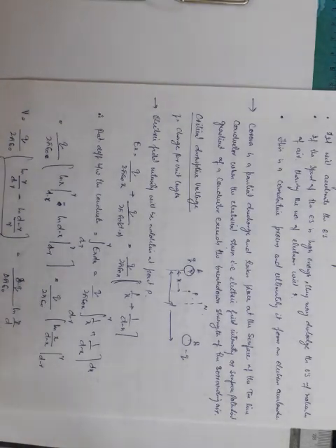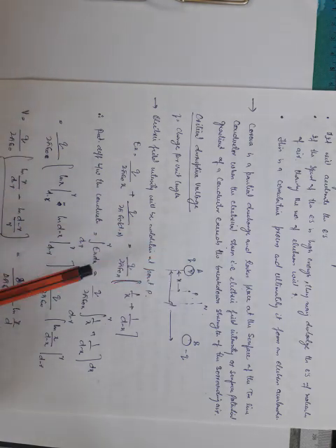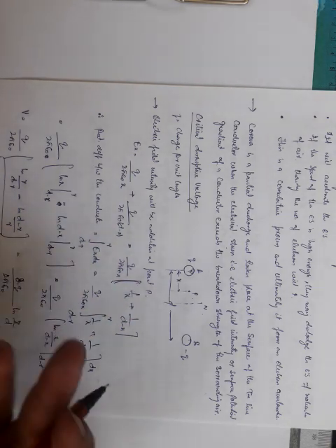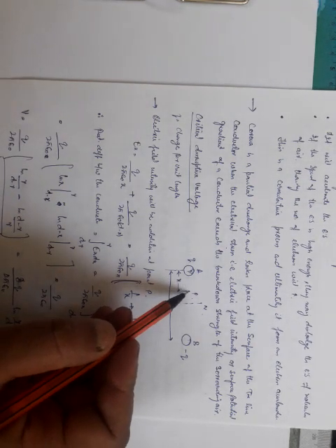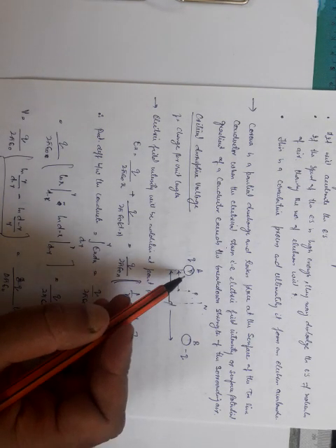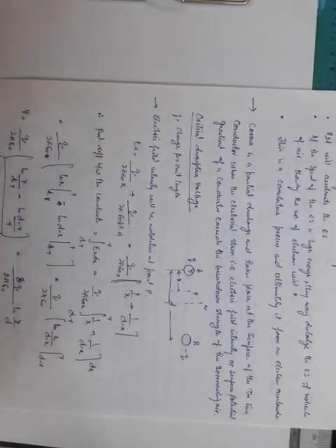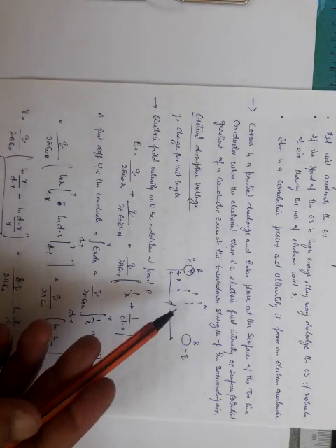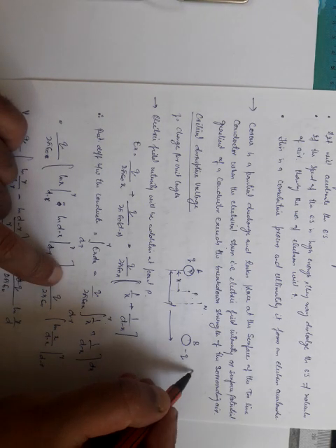Let us take a simple example of having two conductors A and B, where A has a charge of Q, and similarly B has a charge of minus Q, as a return conductor. You'll see that this N is at the middle of the two conductors. Let P be a point which is at a distance x from the center of the conductor A, and D is the center to center distance between A and B. N is the neutral point because in this case it is equidistant from charge Q and minus Q, and the potential at N will be equal to 0.